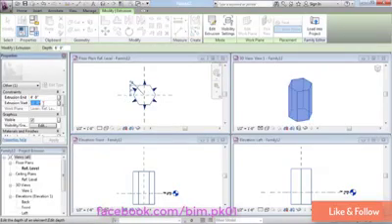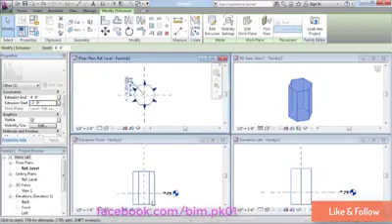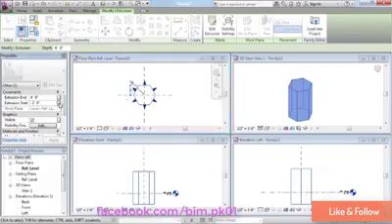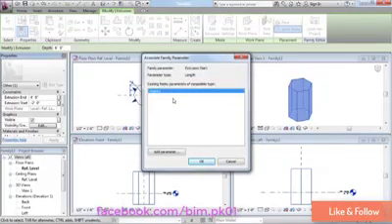So this is one more thing to consider in addition to your work plane: both the positive and negative extrusions. In some of the future movies, we're also going to look at these little buttons over here. I just want to point them out right now, though, and say that this is a way that you can link up parameters to this extrusion and make these values parametric. You could put dimensions on the form, as we saw in the last chapter, but if I click this little button here, I have the ability to link up a parameter directly to that value.